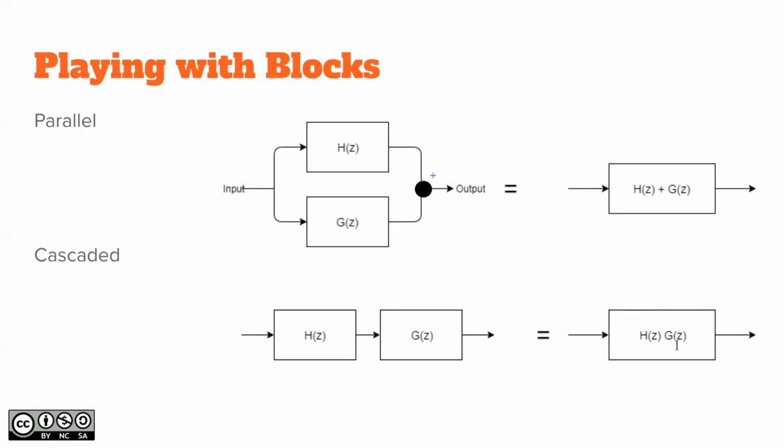For example, if you have 2 filters, you can either have 2 separate blocks to do the filtering, or you can also use a combined system. Usually you will design it as a combined system, and then implement the filter in second order blocks.